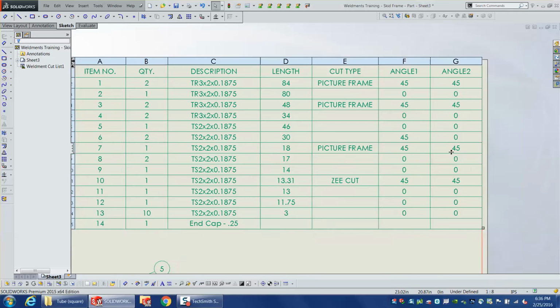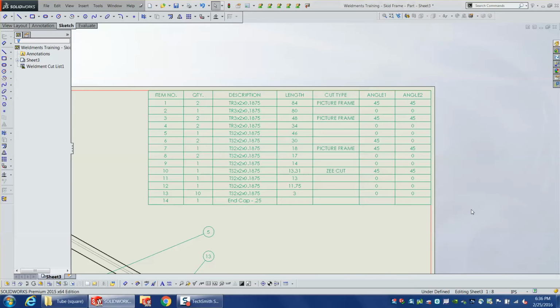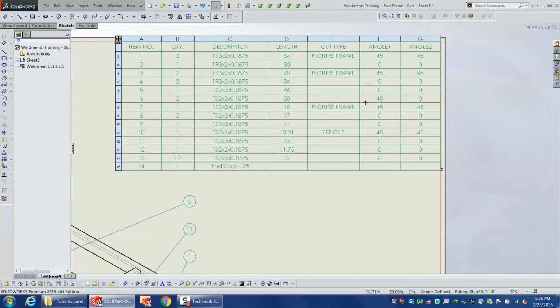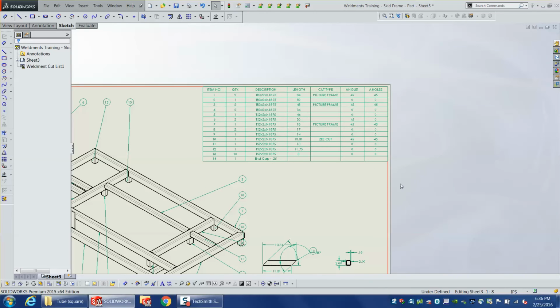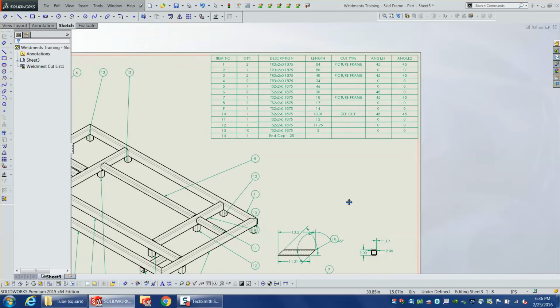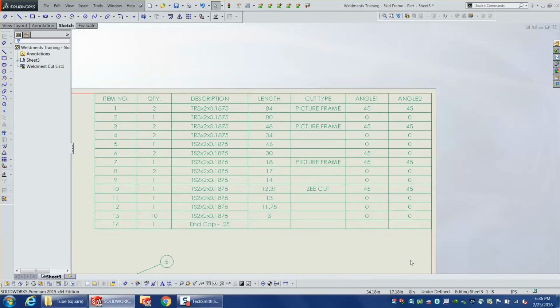So now you can look at the cut list and see, basically I was thinking, I was sending steel to be cut one time and they wanted to know without looking at the drawing which way are the cuts going. I know they're all mostly 45s and they're either all going to go like this or like this. So they wanted that described. You can reference a little picture, and if you have more complicated things, then go to the drawing. Now, is that something you have to type in, or is that something that's... Yeah, I typed that in. So just for those pieces.